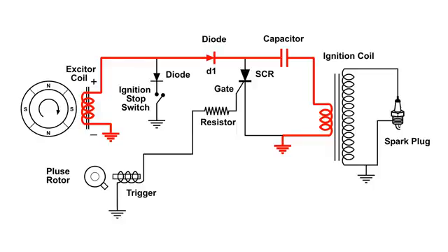Now the magnets have rotated and have induced a voltage in the exciter coil with this polarity, negative on the bottom, positive on the top. And when that happens, D1 will conduct. And here you can see the charge path for the capacitor.